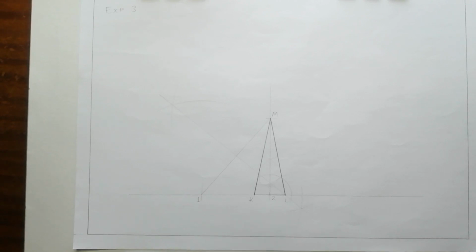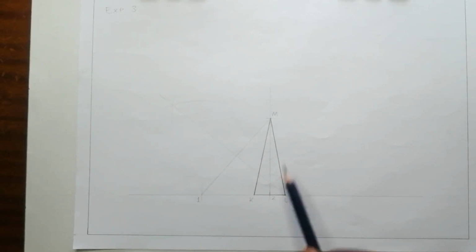A quick recap. First, we draw a construction line where our baseline is going to be. Then we get half our perimeter. We made these marks 1, 2. That's half our perimeter, 50 millimeters. Then at point 2 or even point 1, we make a 90-degree angle. After we make that 90-degree angle, in this case we selected point 2, what we're going to do is get our altitude and mark it on the line from point 2. Then we'll have a point M, which is the vertex at the top of our triangle.